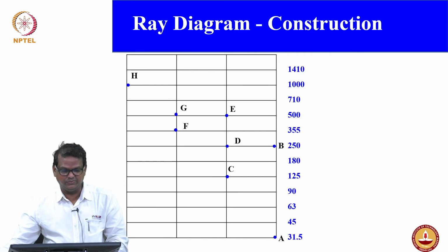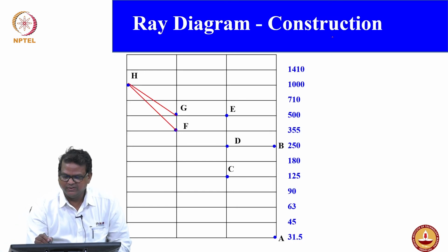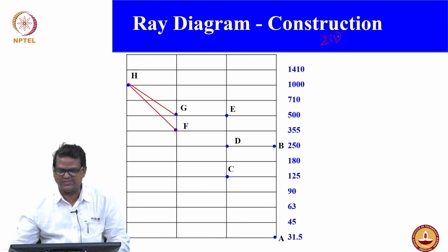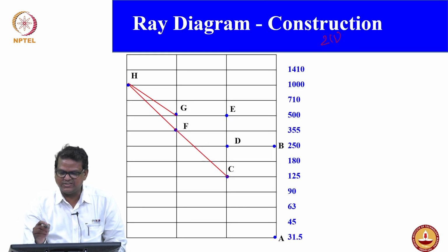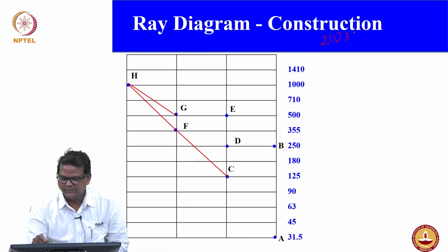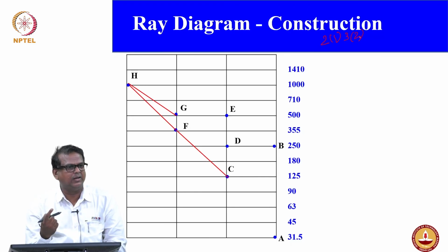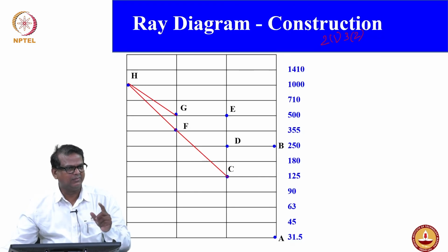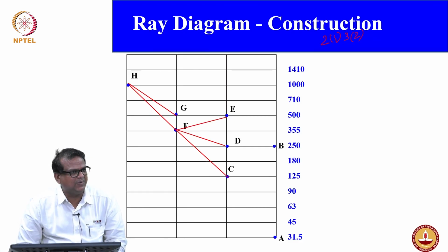Now, how do we construct it? Your input speed splits into 2 output speeds. Remember, 2 outputs from 1 input, that is the first stage. Now, the second stage, 3 of 2, that means for a given 1 input speed I should have 3 output speeds. So, are you getting 3 output speeds?